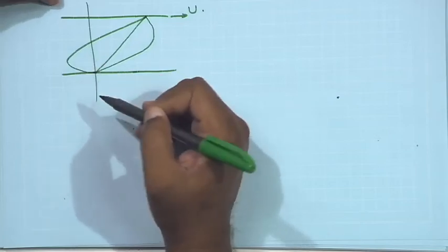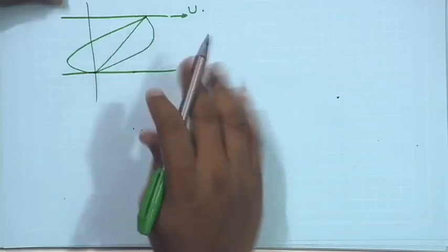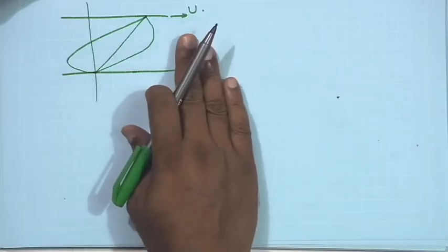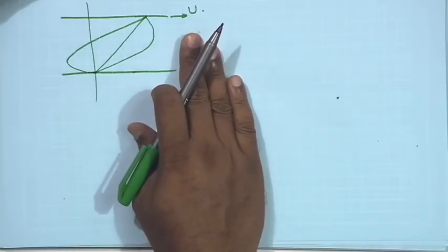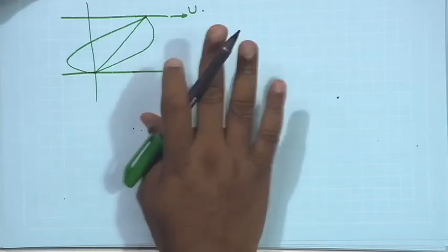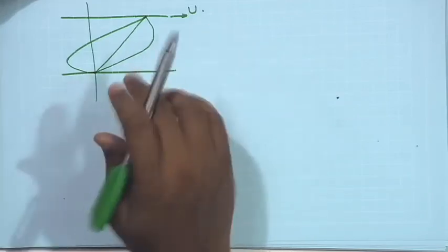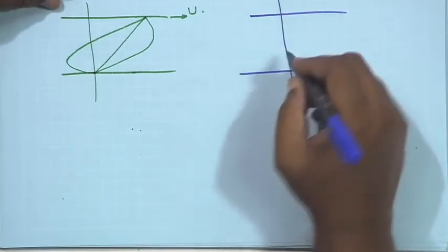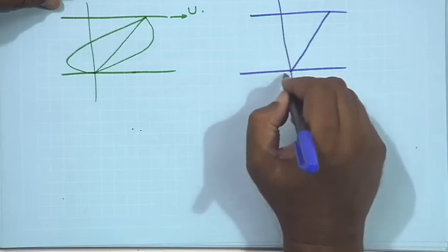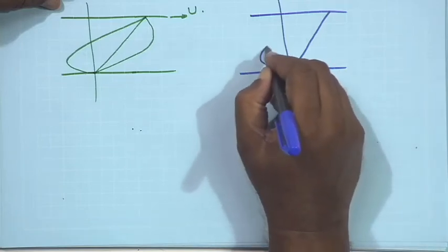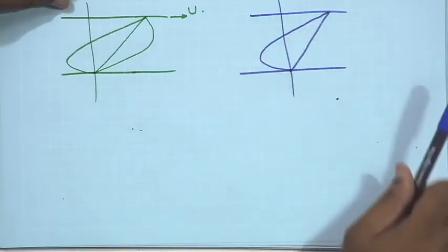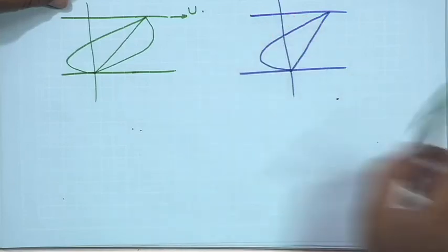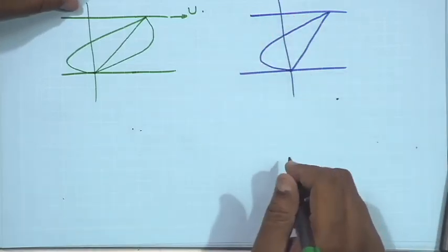So, you should be able to find out the negative pressure gradient. Suppose it is asked what pressure gradient needs to be imposed such that there is no net flow. I am drawing the case for Couette flow and the flow when I have the negative pressure gradient.